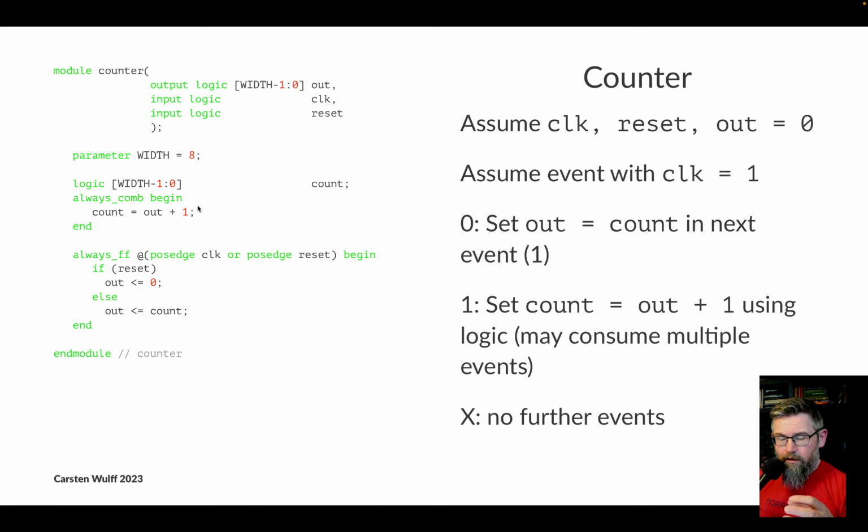So we have split up the counter into always_ff, so synchronous logic, which will turn into flip-flops, and always_comb. I would recommend that if you're writing Verilog, those are the two constructs you use, always_comb and always_ff. That'll help you to think right, because anything that's in always_comb should be combinatorial, and anything that's in always_ff should be synchronous flip-flops.